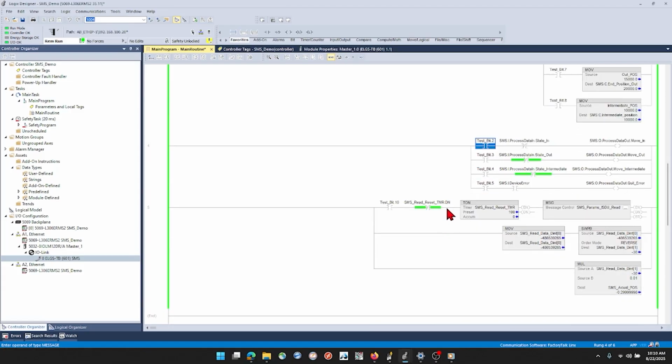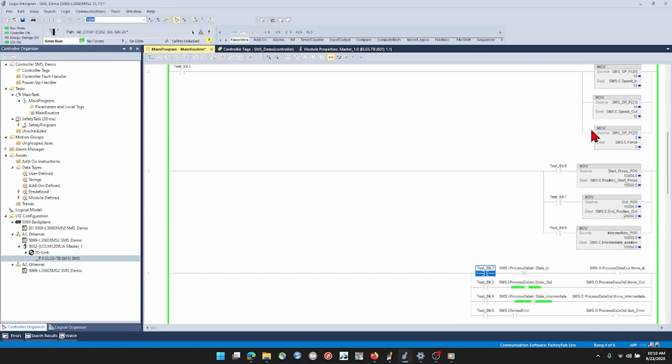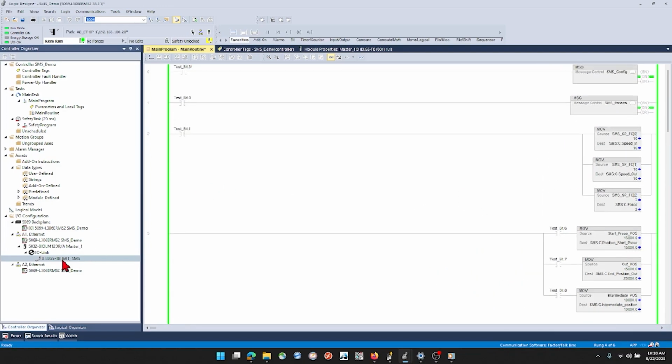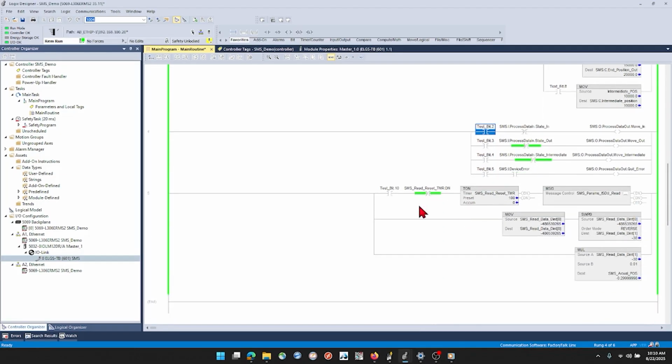So I do want to show you one more thing real quick. I know this video is getting to be a little bit long, but we've had a couple of customers ask us, well, this is great, all this is nice, and you can do this very easy with the new ArmorBlock IOLink Master, but where do I see my actual position of the actuator? So that is not one of the tags that's in the configuration, your actual position. So I just wrote a quick routine here to do an explicit read message from the IOLink Master down to our device to get this information. So I want to show you guys how this is set up real quick.